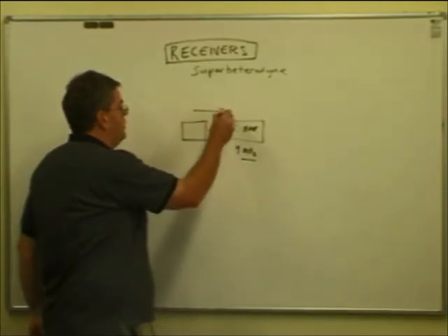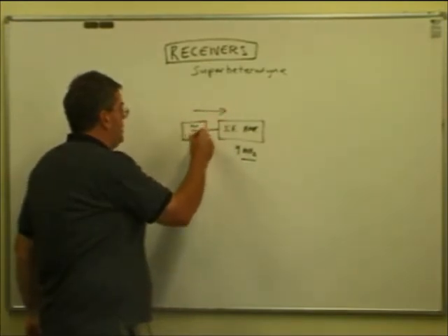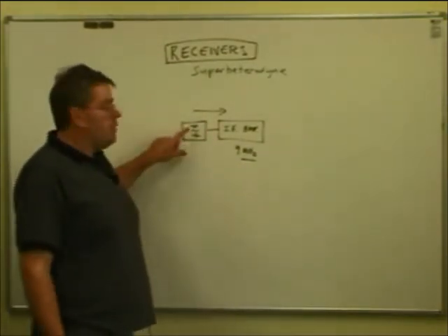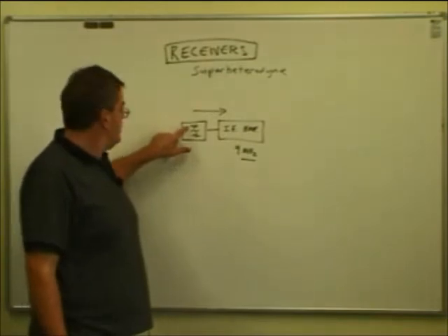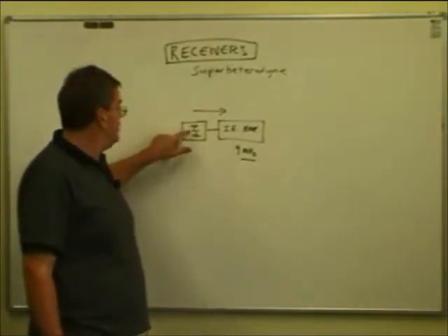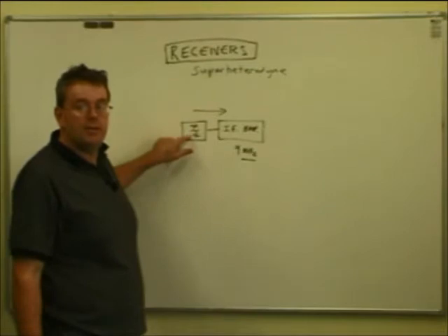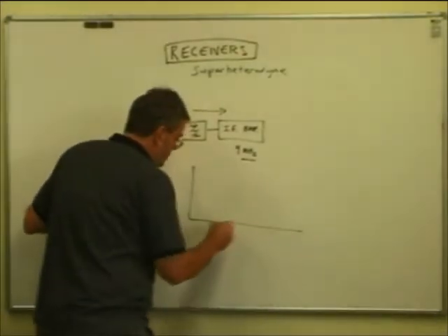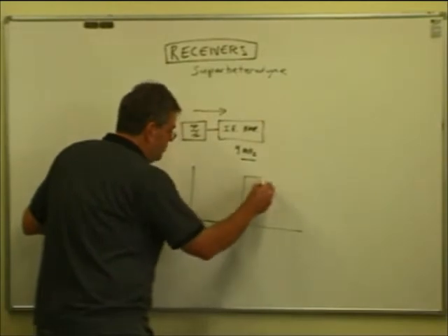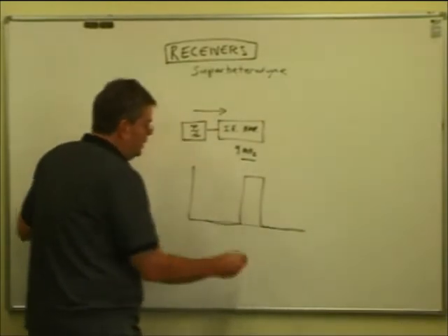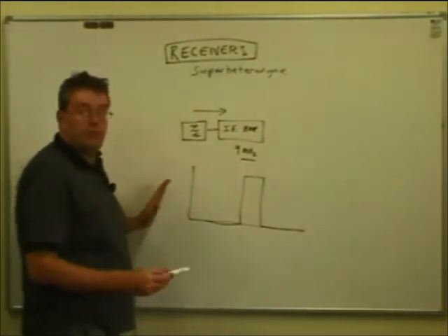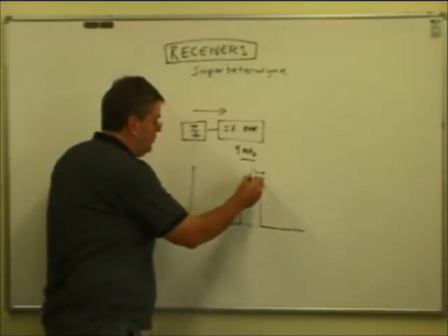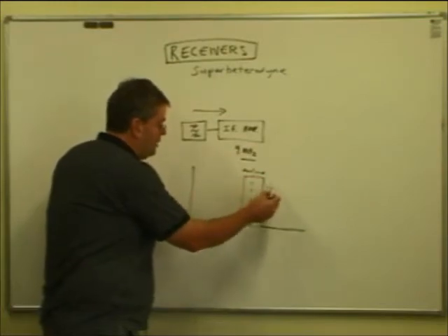Here's the way the signal's going: a band pass filter. There's the symbol for a band pass filter. It won't pass frequencies above the frequency you want it to pass. It hasn't got a line through it for the middle one, and the frequencies below it's got a line through it. In other words, it's a filter with a response like this, and ideally it's pretty sharp like this. So, for instance, if it's centered on 9 megahertz, it will just pass a little bit above, a little bit below, but outside that range, nothing.